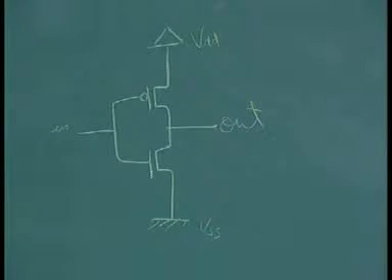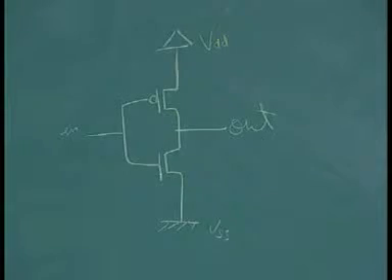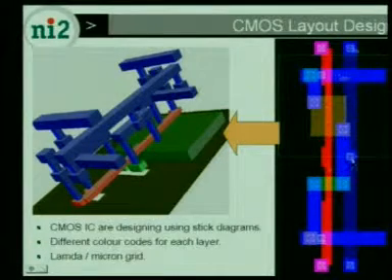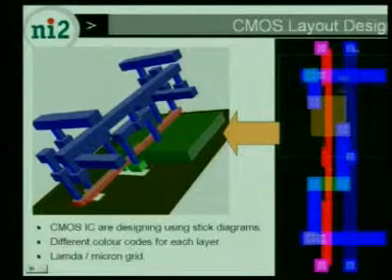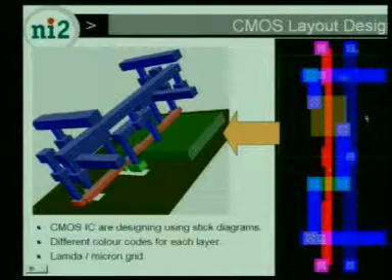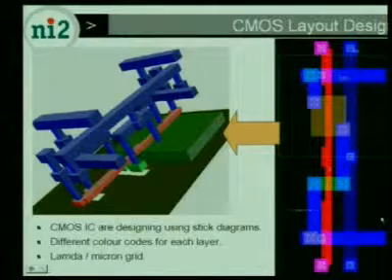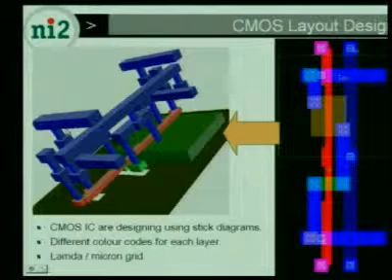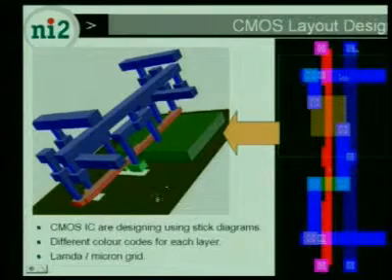So, this is a basic CMOS inverter, and this is what I have done here. I have made this gate common; this red one is the gate for this NMOS and PMOS. I have taken the output from this one, and this is the metal 2 layer, metal 1 layer. I will explain later why we are using different kinds of metal layers, what the purpose is, and how to optimize this circuit. This is not the optimized circuit, and you can see this 3D view, it looks like building blocks. This is your P type and N type, and this is by default the P type substrate.